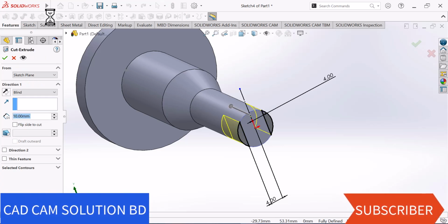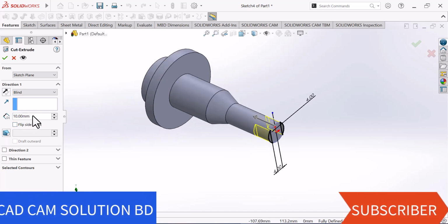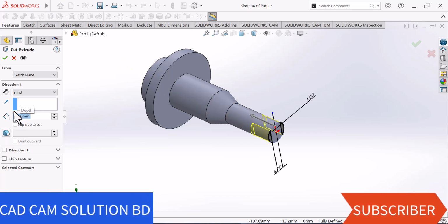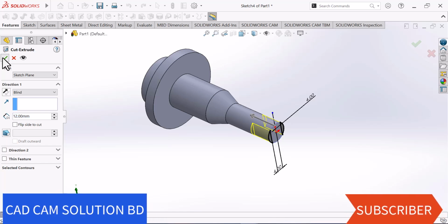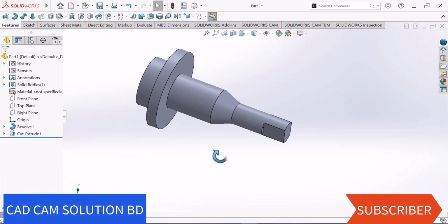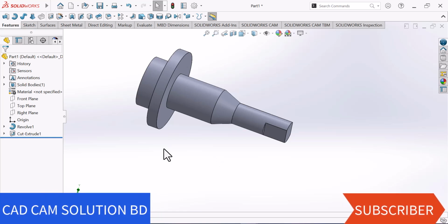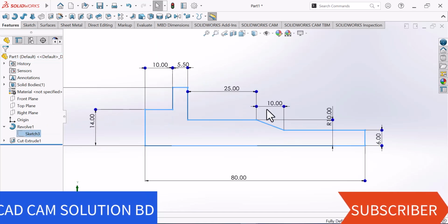Okay. Now go to feature and select extrude cut. Now give the value here 12. Okay, select. Now go to this sketch again, edit.